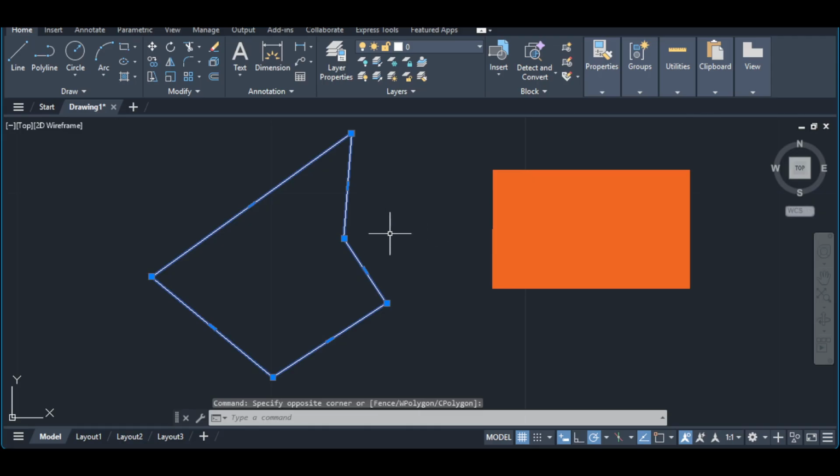Closed shapes are essential for creating 3D solids, so if a boundary looks like a loop but still won't behave, there's probably a small gap to fix. Keep an eye on your current layer as well, because the solids you create will be placed there. If you need them on a specific layer, set that layer current before extruding.